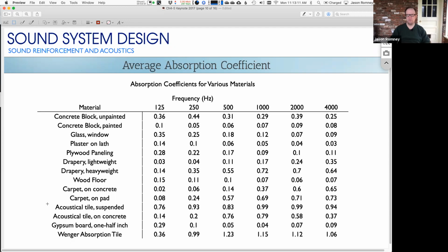So like if we were back in our lab right now, I could show you in the corners, you might have remembered that we have those acoustic panels and we corner load them. And there's a gap behind there. And those are bass traps, okay? The idea there is to give a little bit more space for those low frequencies to get absorbed. We're effectively making that thing thicker.